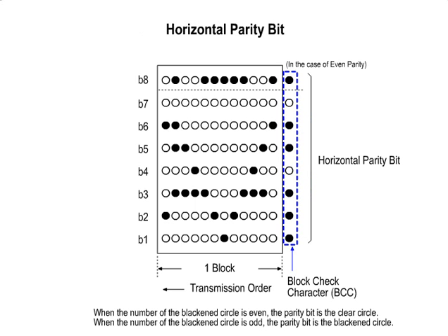B. Horizontal parity check method. Characteristics. A parity bit is added in the horizontal direction to each block, which is the transmission unit for data transmission. In addition, a vertical parity bit is also added to this code and checked. This single character redundancy code is called the BCC, block check character. Disadvantages. If the even bit in the block is mangled, the check cannot be done.